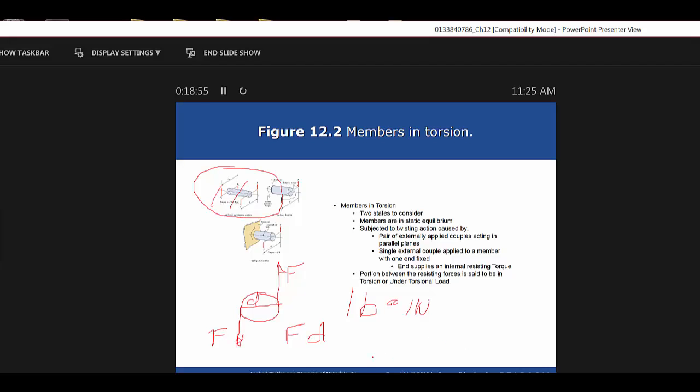That's what that little dot in there means, pounds inches or pounds feet. You have 12 inches in 1 foot, so you'd be dividing it by 12, and then you'd be at pounds feet. Now, the nice thing about it is if you get the right torque wrench, it's all done for you, right? Get one that's digital.